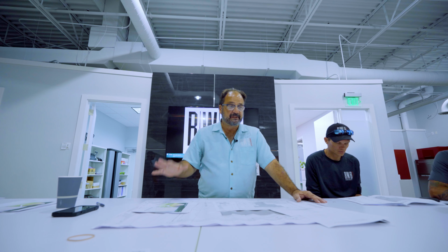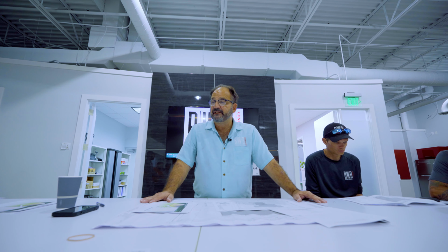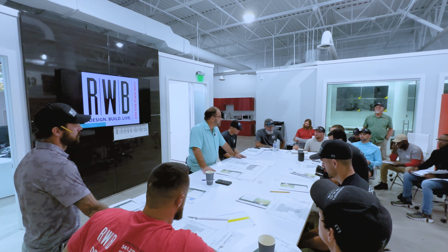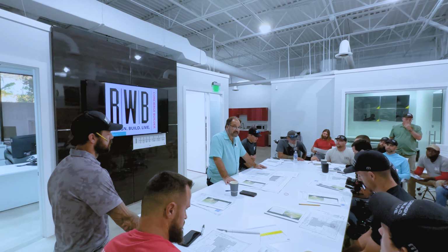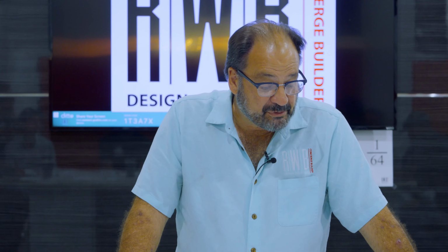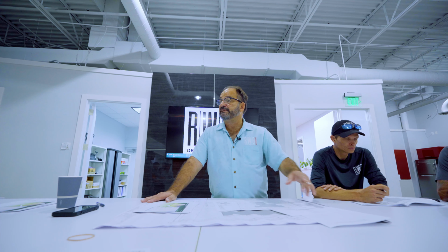So take these and get comfortable with them. Be comfortable with grade. Make sure you understand what it means. If you have a question, Dan, myself, anybody here can go through and give you help with this, okay? The intention here is for you guys to understand what you're doing while you're doing it. When you're on a job, look at the drawings that are there. The guys doing the grading, the surveyor will come out and check points. When we do the driveway, the surveyor will come out and give you points around the driveway to make sure your curve is right. He'll actually mark on the stake he puts in what the elevation is there that's supposed to be finished. So we're getting it rough, and then we're going to fine tune it.